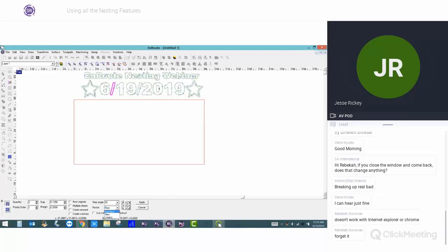So sometimes if you do standard and you click the bottom left, what you'll get is the L shape. You'll actually get it to where it nests in the front of this sheet and then along the long side as well, which if you're cutting the scrap material off, it's not as easy. Whereas if I click new, I can say, go ahead and smash this to the front. So that way I can just make one clean cut and be done with it.